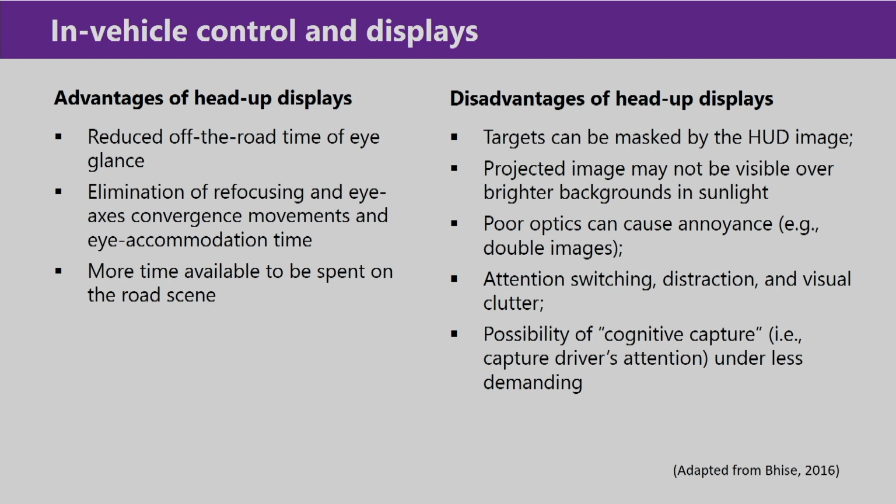On the other hand, there are also some disadvantages. First one, the target can be masked by the head-up display image. Second one, the projected image may not be visible over a brighter background in sunlight, in bright daylight condition. Poor optics can cause annoyance. There may be double images. While drivers are looking at the head-up display, due to poor optics, they may find double images, which may create annoyance for them.